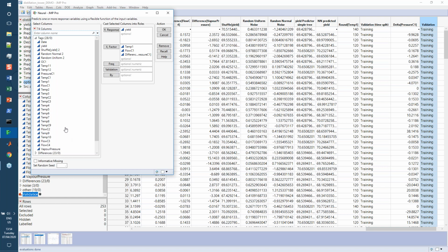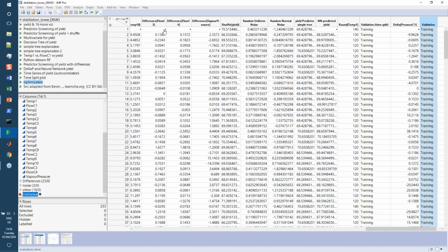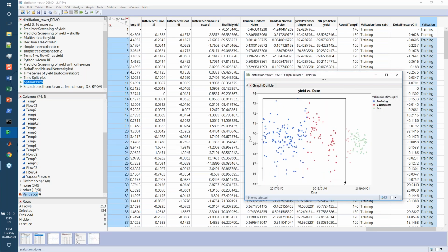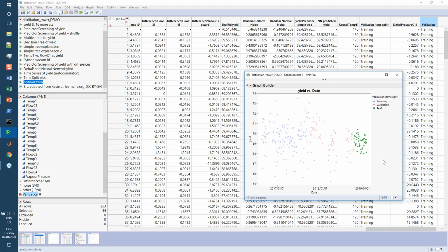Any model in JMP has access to specifically decide what validation you want to add. And this is very important, because here I will use this data for model validation, and I will use this data set for the test. So this is not used at any moment in the model. In machine learning, this is for fitting, this is to avoid overfitting, and this is to test that